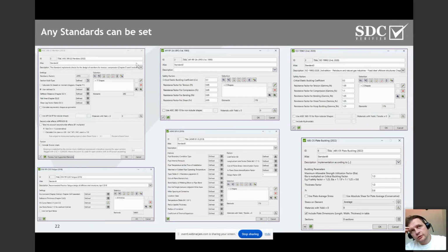Buckling analysis from solver gives you a buckling factor for one panel. You stiffen that panel, it's okay now. You rerun the buckling analysis with solver and you get the buckling factor for the next panel. So that's an endless loop. Code check gives you buckling strengths for each and every plate and panel in your model. So that's why it's much more convenient to use, because you know that your complete model is correct within one iteration. Well, or maybe incorrect, but then you know all the panels that have to be stiffened.